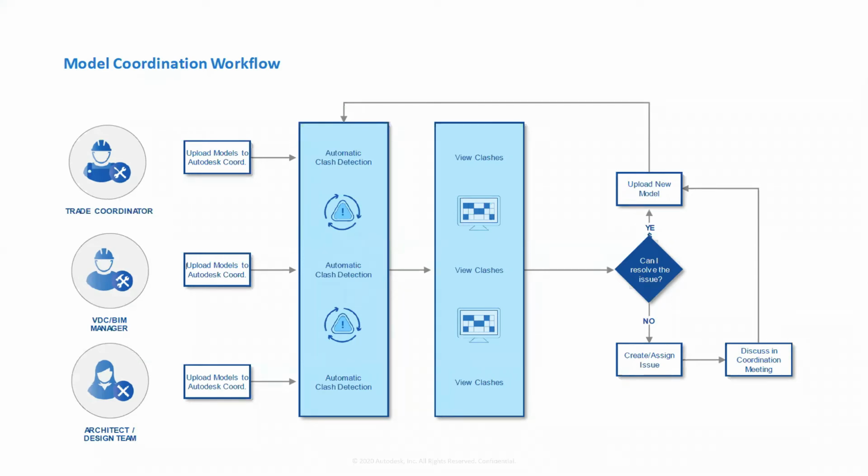If you have a look through this example, I won't go through all of this, but the middle line there gives an example of a manager that is potentially uploading models to that automatic clash detection location folder. The tool, BIM Collaborate, is then reviewing those models and creating those clashes automatically and updating the matrix. The clash matrix, which I'll show you on the next slide.